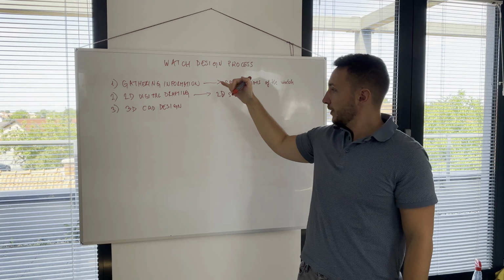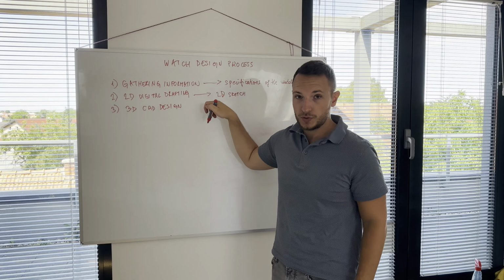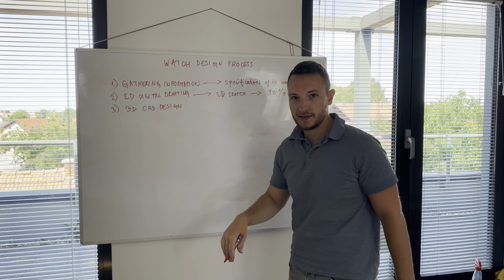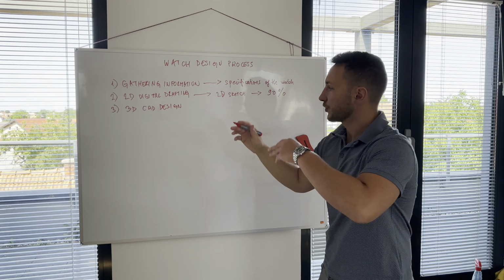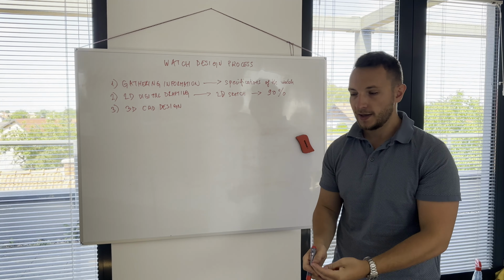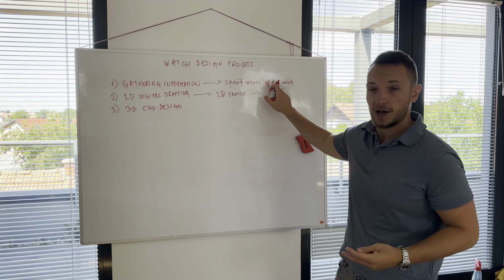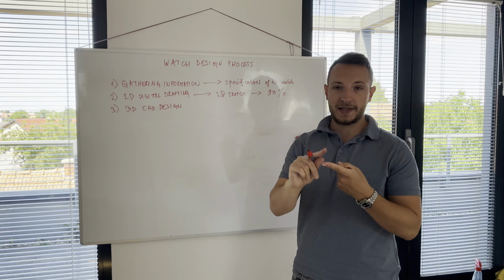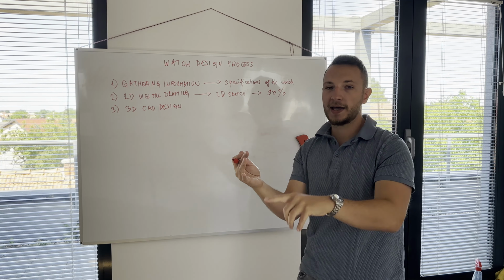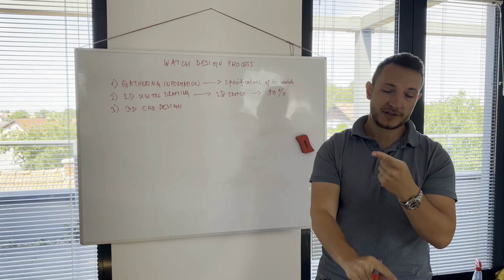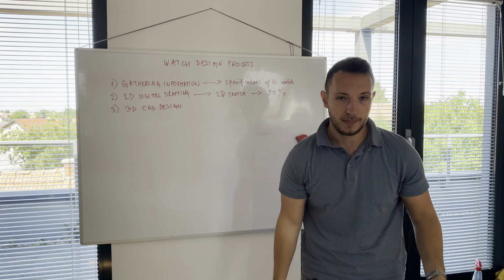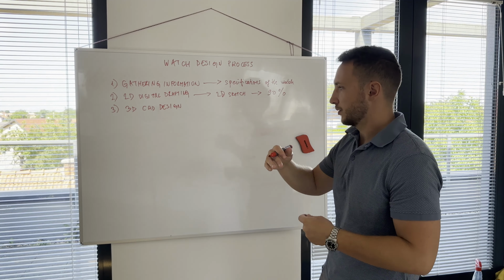So when we have all the information, and we've made a 2D sketch of the design that is at least to some degree completed, let's say 90%, the rest we'll fix in the 3D design. Here we start off engineering and designing the actual components of the watch. Firstly, we take the movement from the specifications of the watch, and around that movement we will be designing the case in 3D. We will be designing the bezel, the caseback, the movement holder, the dial, hands, glass, crystals, gaskets, end links, the complete metal bracelet, or whatever kind of leather or rubber strap the watch will have.